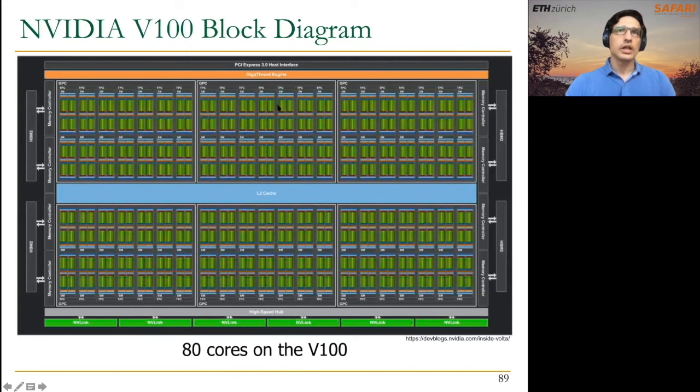And then the cores can access the external memory, which is the global memory, DRAM. Typically, in this case, it is HBM2 memory, which is a special DRAM that is built by using different layers of DRAM and connected in a special way, using a lot of lines from the stack of memory to the GPU, and this way we can extract much more bandwidth. You will learn about memories in later lectures.